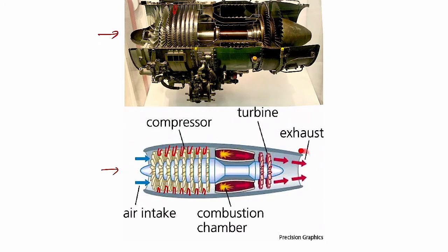So right at the exit, there's typically a nozzle so that you get a high velocity. You want the velocity coming out of the back end of this thing to be as high as possible for a jet engine so you get a lot of thrust. That's the whole point of a jet engine, is you want to take that energy that you've added into the flow through the combustion process here and turn it into kinetic energy out of the back end so you get a lot of thrust. The idea behind thrust and how you analyze that is discussed in ME 309, the fluid mechanics course, so we won't discuss it here. But usually there's a nozzle here that accelerates the flow and turns some of that thermal energy into kinetic energy.